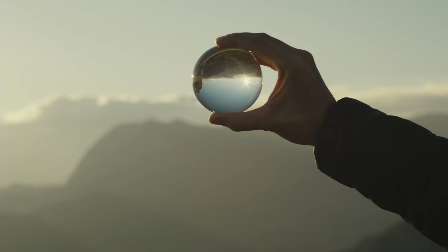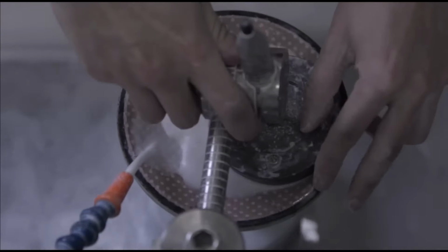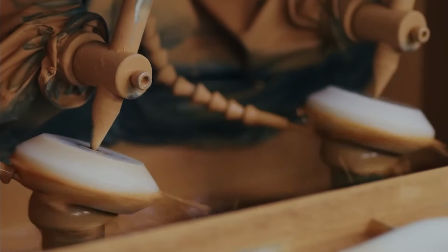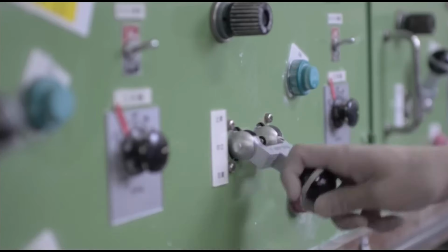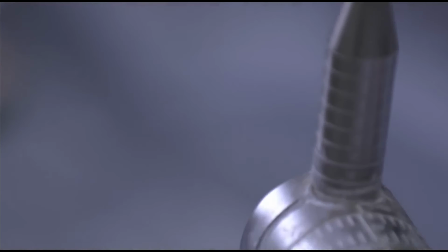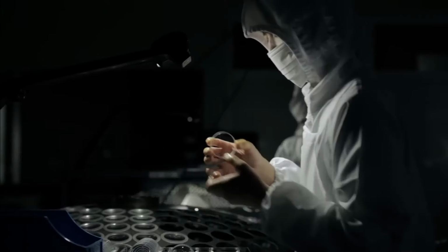The lenses are set up on circular racks, affectionately known as planets, and put within a vacuum chamber. Inside, an electron beam evaporates the coating ingredients. After 3 hours of obtaining this protective finish, the lenses are thoroughly washed to eliminate any residue. Each lens, whether concave or convex, is thoroughly inspected and cleaned.